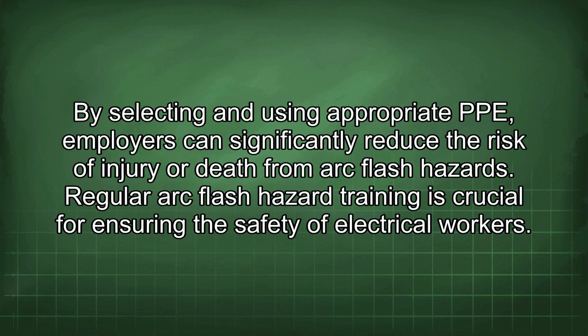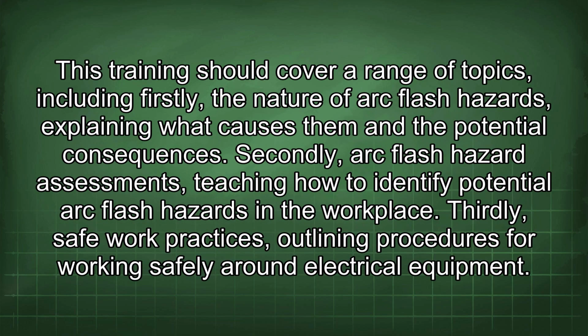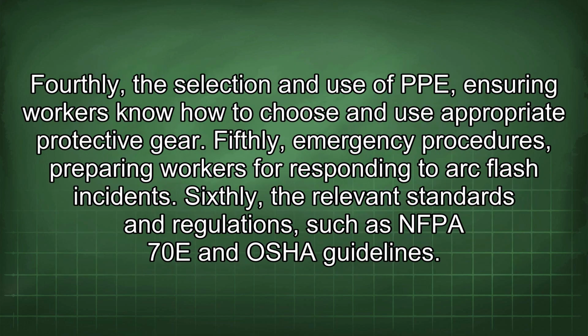Regular arc flash hazard training is crucial for ensuring the safety of electrical workers. This training should cover a range of topics, including, firstly, the nature of arc flash hazards, explaining what causes them and the potential consequences. Secondly, arc flash hazard assessments, teaching how to identify potential arc flash hazards in the workplace. Thirdly, safe work practices, outlining procedures for working safely around electrical equipment. Fourthly, the selection and use of PPE, ensuring workers know how to choose and use appropriate protective gear.